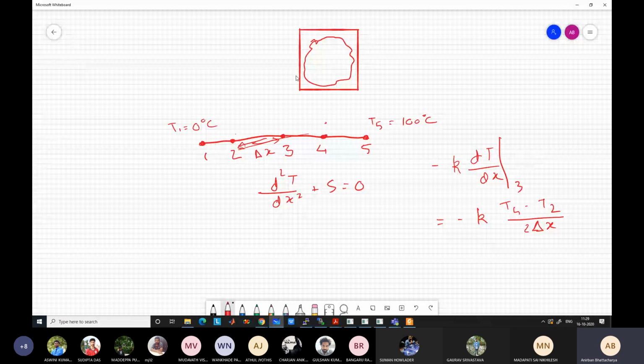Divide it into straight lines like this. Okay, so all the control volumes are still similar in nature, rectangular type. So like this you have to divide, and now what you have to do is formulate the equations so that the equations also take into account the boundary effects.